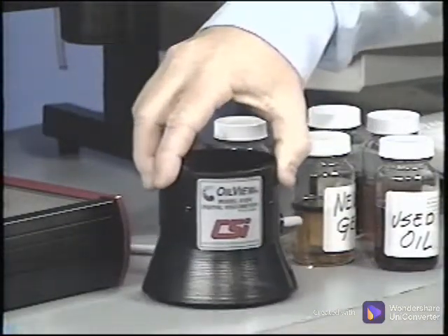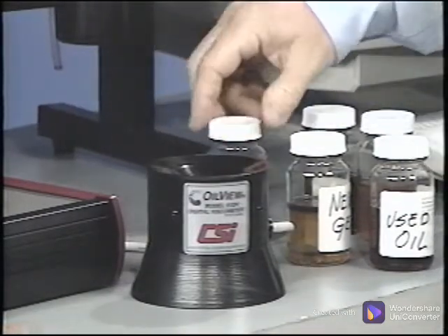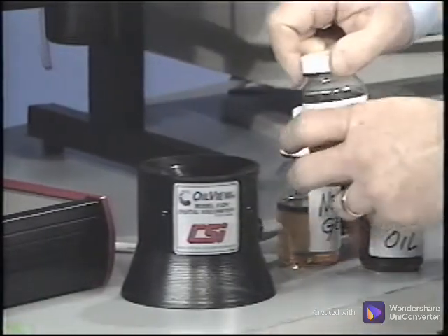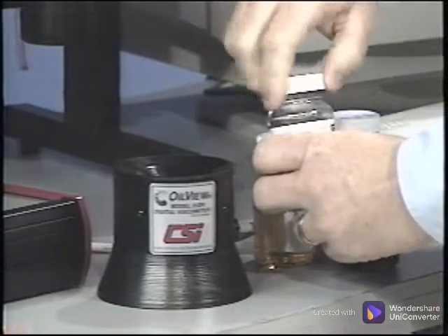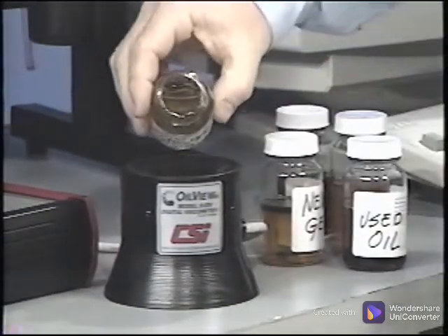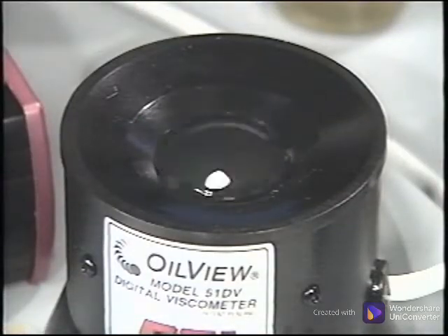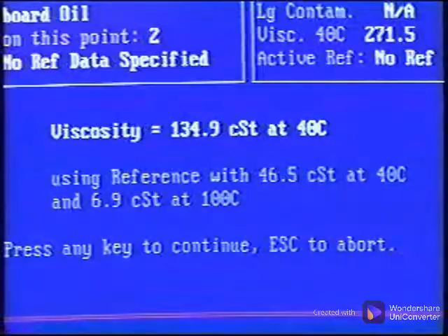This digital viscometer uses a patented free rotor system to measure viscosity and the oil temperature, recording the information in a database to be used in conjunction with other analyzers and devices to trend your oil condition. Compare this measured viscosity against the machine manufacturer's recommendations and against new oils to verify they are correct.